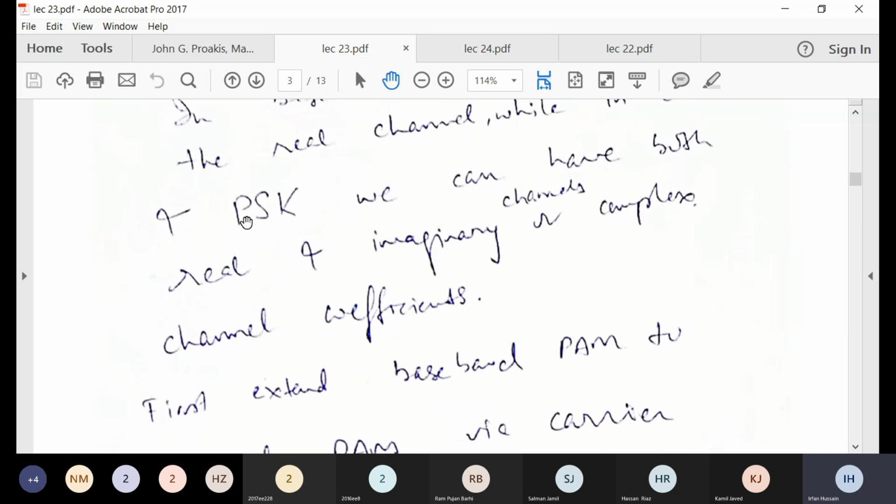But for now, for PSK and QAM, you have actually 2 orthonormal bases, but for PAM you have only 1. If we are using sines and cosines for the passband representation, a real axis is more than enough for PAM, but for PSK and QAM you have both axes, cosines and sines, or the in-phase for cosine and the quadrature phase for sine.